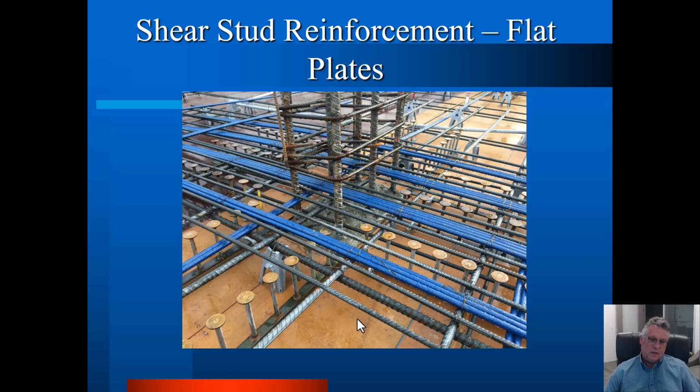But you know, that name has just transcended the whole industry, and everybody calls these stud rails now. They're technically headed shear studs, welded headed shear studs on rails, but we call them stud rails, and Dirk seems to allow everybody to do that. But that's the shear reinforcing.